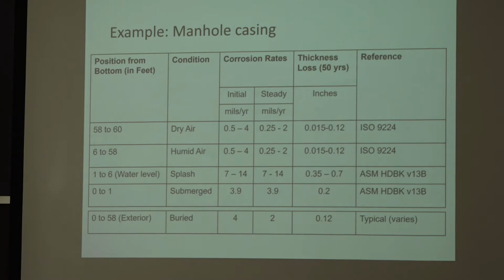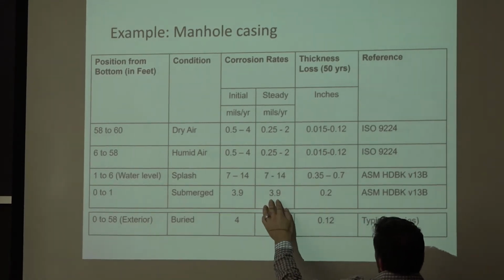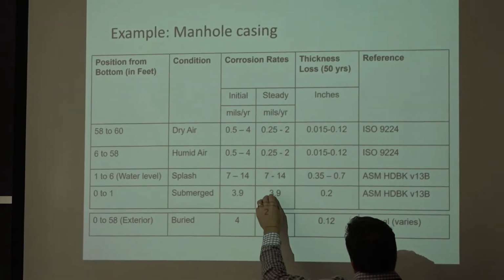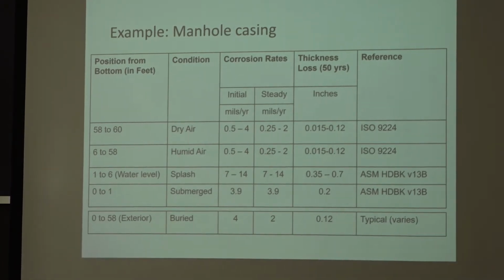And the chemistry, so there are some steels called weathering steel that form a different oxide that is more stable on the surface. So there are two or three possibilities, but here it's really to give you just a general sense. If you have a working tool, like a shovel that you leave outside, that's going to be in rain sometimes, but not all the time, the steady rate here is significantly less. It could be about 1/10 of what happens if it's submerged all the time, but in certain conditions it could be just half, so very close to what happens in submerged water.